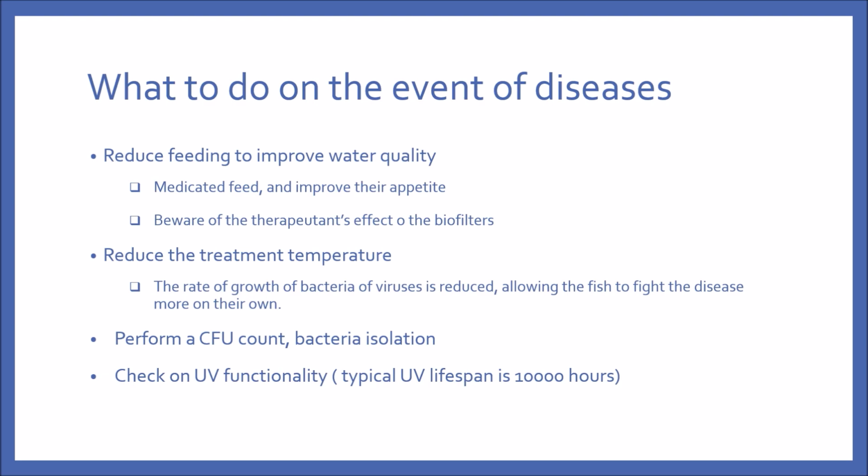In the event of diseases, try to perform a CFU count. A CFU stands for colony forming unit, and it gives you an indication of how much bacteria you have in the system, and try to isolate the bacteria to know what you're dealing with. Check on your UV functionality. The typical UV light lifespan is about 10,000 hours, which equates to about 10 months.